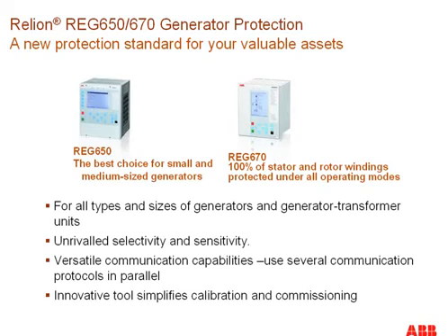And it has unrivaled selectivity and sensitivity. Lots of communication capabilities are provided in all of our REG type of relays. In fact, it is for all the Relion series. We can provide DNP3, IEC 61850, and other communication protocols as well.